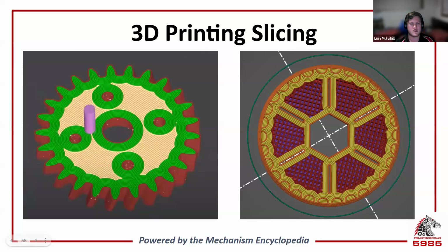For the lower infill percentages, you can add small slits in your design to force the slicer to add walls in that area. This makes for added strength in your print. So we have a pulley here and a gear here. A pulley on the right, gear on the left. These can also be used in conjunction with the inserts for having the best torque transfer.